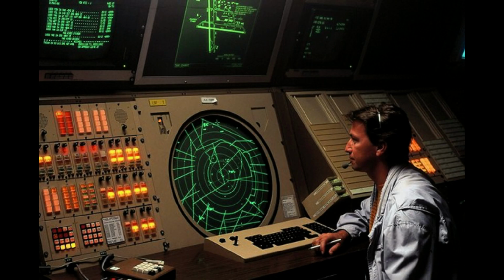Radar departures. A radar departure is another option for departing an airport on an IFR flight. You might receive a radar departure if the airport does not have an established departure procedure, if you are unable to comply with a departure procedure, or if you request no SIDs as a part of your flight plan.